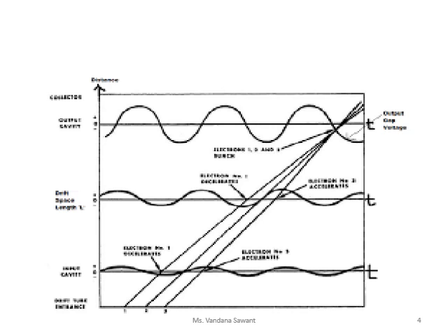And this current is having many harmonics. If you compare this current to the input current, then there are many harmonics of your input signal present in the catcher cavity. So you can have a minimum of 15 harmonics of the input signal in the catcher cavity.